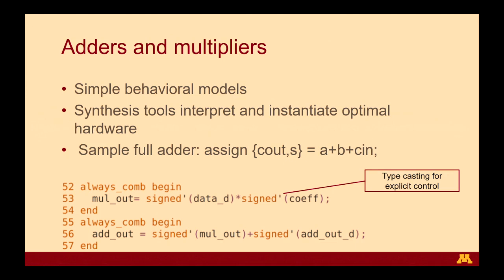These are very common sources of error when you do Verilog design, because the tools do not know whether you intended to truncate the result or not. But you should be able to do that in another line of code. Keep, say, 12 bits of a 15-bit result, in one more line of code. As the Professor stated, in these kinds of scenarios you would want to have the ultimate control of which bits to keep.